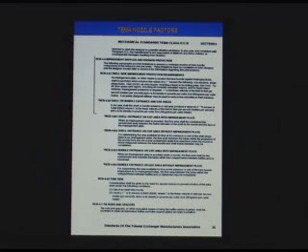As part of the HTRI program, we have a vibration printout which will give us a potential warning for vibration. We check the nozzle velocity, nozzle rho v squared. We check the entry rho v squared. That's basically the distance under the nozzle to the impingement plate, and ensure that that is adequate so that we do not have any vibration.